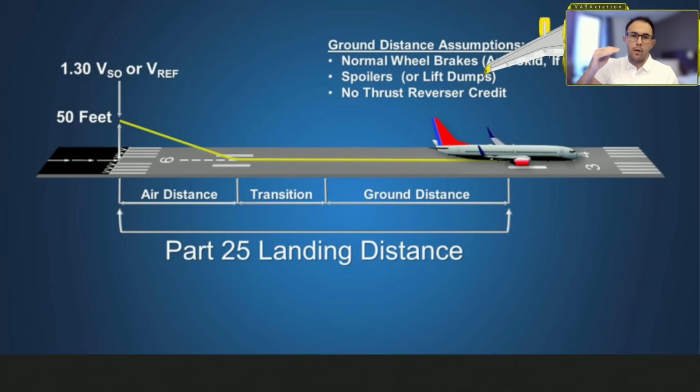So if our landing speed, which I will talk about here in a second, is 90 knots or less, our approach category will be A or Alpha. If the landing speed is between 91 and 120 included, our approach category will be B, Bravo. If our landing speed is between 121 and 140 knots, our approach category will be C, Charlie. And if our landing speed is between 141 and 165, our approach category will be D, or Delta.